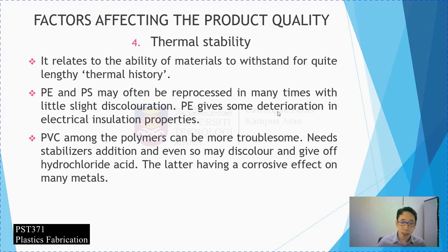Usually what we do is we measure the operating temperatures of this raw material using the DSC itself. When you use the DSC, you measure the starting melting temperature until the end point of melting temperature. This is the operating temperature of this raw material. So you need to take a precaution.